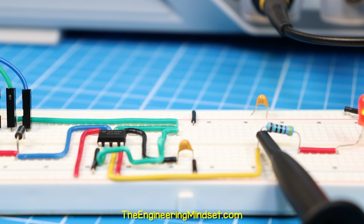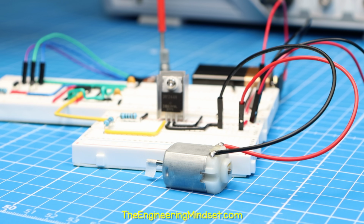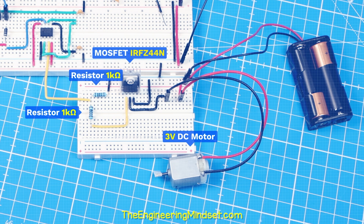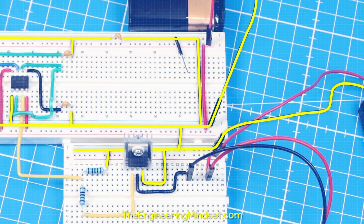But if we swap the timing capacitor for something much larger, the frequency decreases enough that we can see this with our own eyes. We can also use this circuit to control the speed of a DC motor. We need to modify the circuit with a few extra components. I'm also using a 3-volt supply for the motor, but the grounds are connected between the two power supplies.